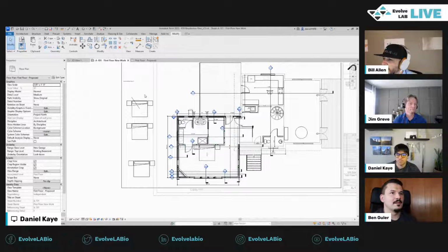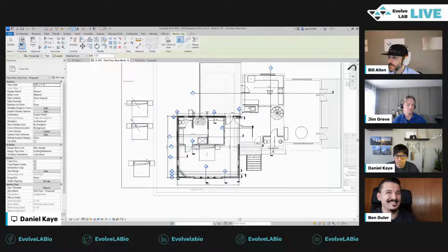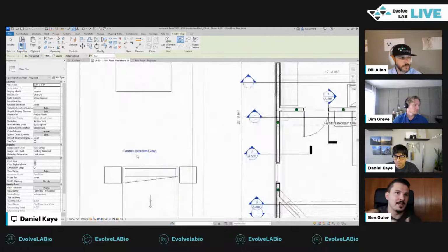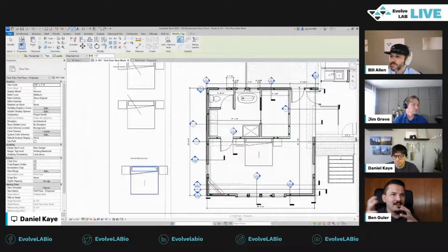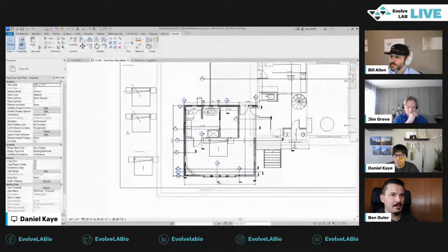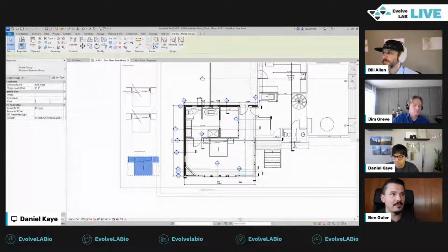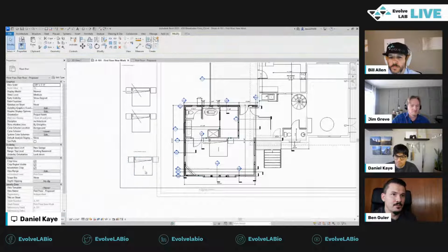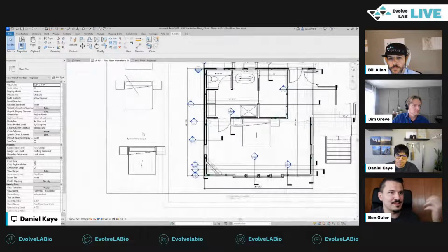Large, yeah. I think there was the whole kind of workflows with units and multifamily where you have a group versus a link. And now that you could tag them individually, the tags could actually stay on the link side. I think we used to try to put some annotations inside the link, because we do have annotations from the link, like dimensions and whatnot, but you can't have that automatic tagging. You'd probably do a dumb thing for it, but now you could do it parametrically like you could with every other thing in Revit, which is, I think, amazing. It enables more workflows for both of those groups versus links setups.